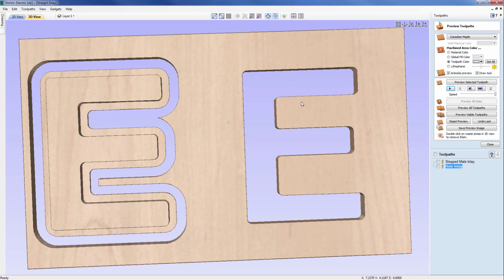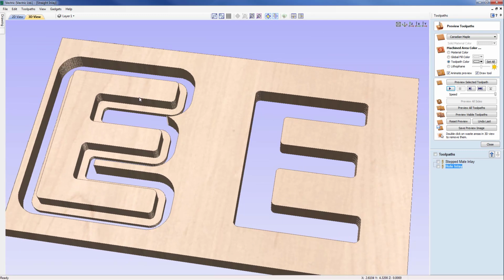But of course, one thing that we have noticed here is that the height of our letter is just 0.375 here. So that's the height there, because we still have essentially a 0.125 inch step there. And on the right hand side, our female is a full 1/2 inch. So essentially, if we do push this in from the back side of the female, we will be sitting down from the top by 0.125 of an inch.